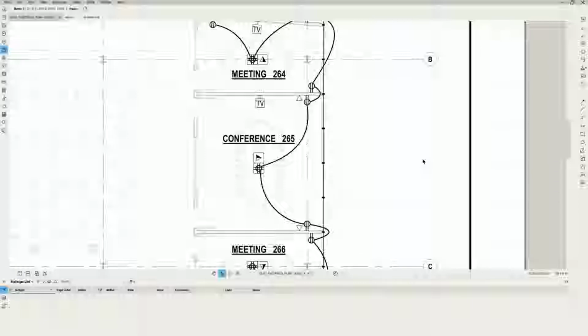And first thing we're going to talk about is punch lists. And the workflow for that punch list is really we're going to create some spaces, and then we're going to create a stamp and use tools and markup lists to kind of keep track of punch lists. Punch list items really deal with issues and when people go through and inspect portions of the work. And it can be done by a myriad of people, anywhere from architects doing final punch lists to subcontractors doing punch lists of their own work to general contractors walking through the building looking for safety issues and the like.